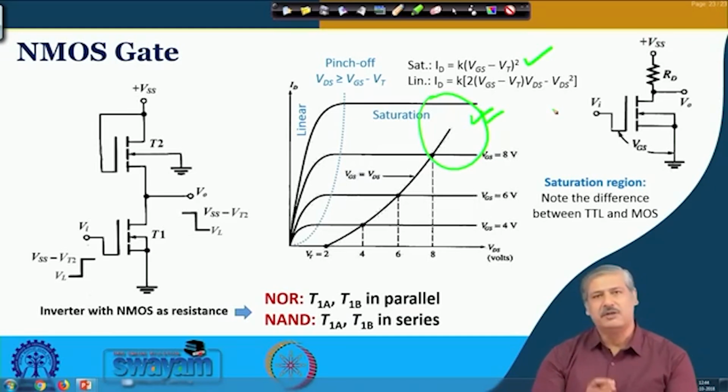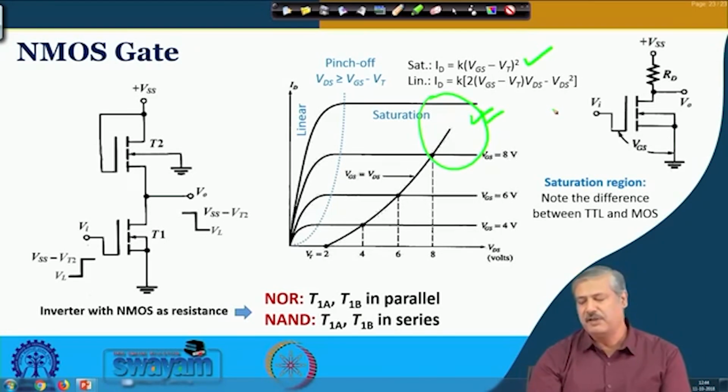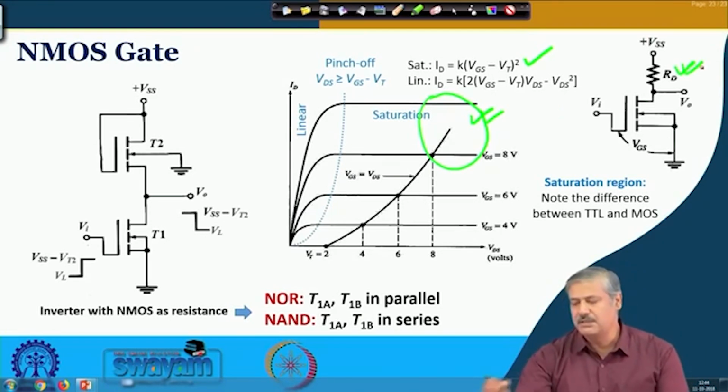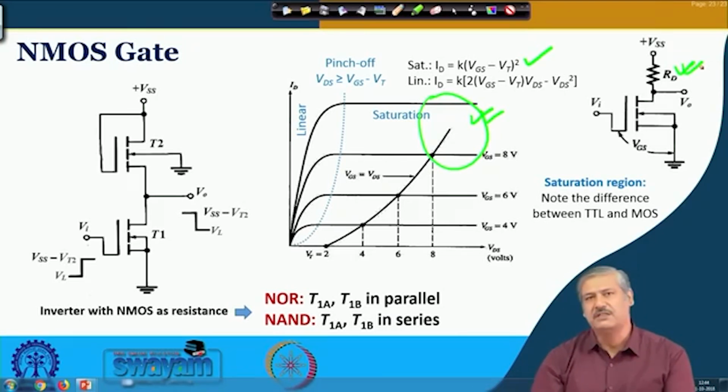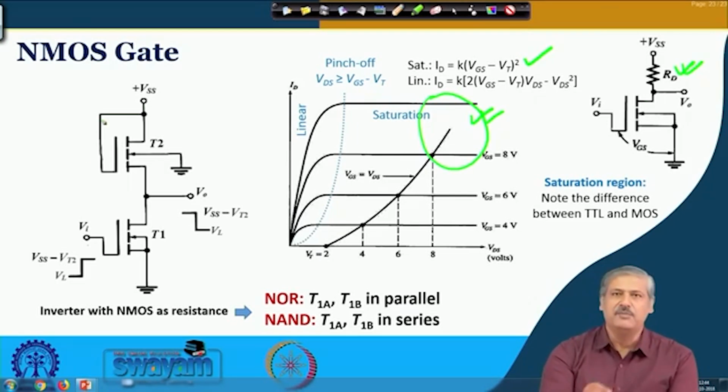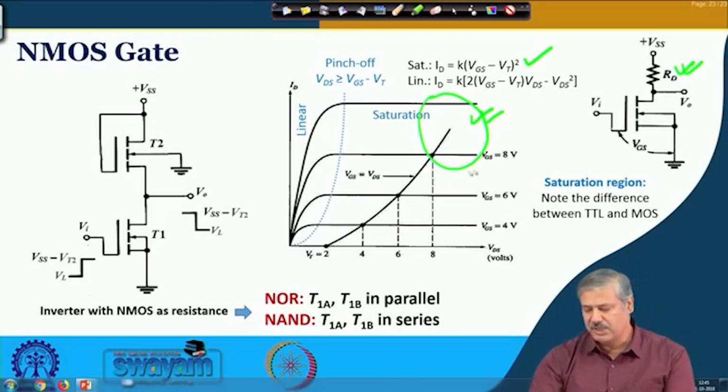In NMOS based logic development, manufacturing resistances, which are now very high, takes a lot of space. So instead, an NMOS transistor based load is used, with gate and drain connected in this manner, which offers an approximately linear characteristic when VGS and VDS are constant.